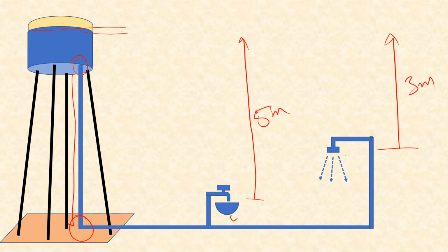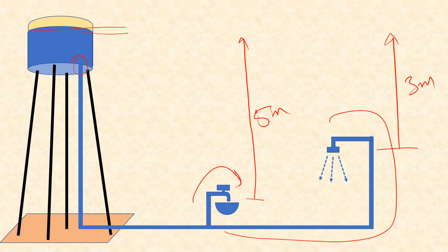So using those head losses at different points, we can form an equation for this setup. Then for this setup, we can again form a second equation, which will be again, you'll add head loss at entry through this length, at bend, at this length, and at this length, then this bend, and in between there will be an additional loss at this T joint.